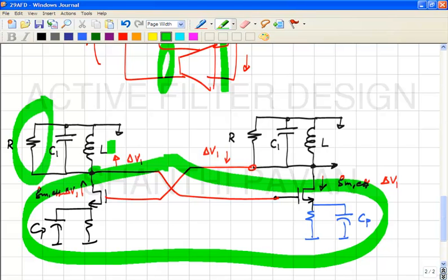R. Okay. So if you have to fix the stability, you have to reduce R or increase R? If you want to damp the tank even more, if you increase R, what happens to the poles? Q increases. That means it's more damped or less damped? Less damped.